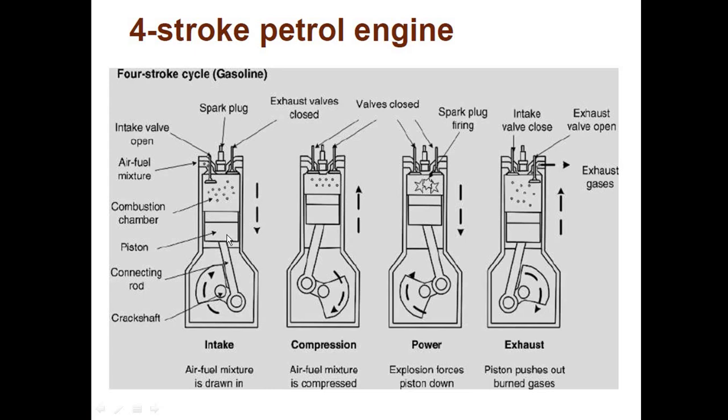As the piston moves from bottom dead center to top dead center, the fuel-air mixture inside the cylinder compresses from BDC to the clearance, that is, from the total cylinder volume to the clearance volume. As it is compressing, its pressure and temperature will increase, and this compression is carried out isentropically or adiabatically. At the end of the compression, this is the second process.